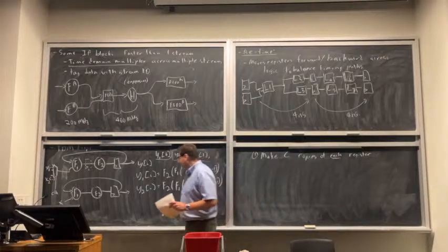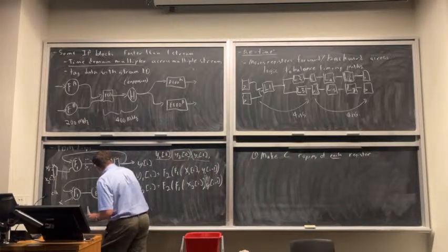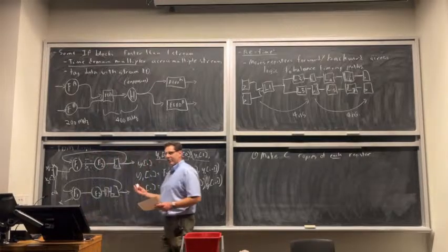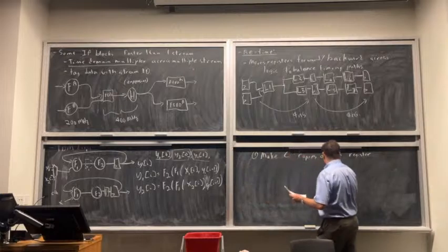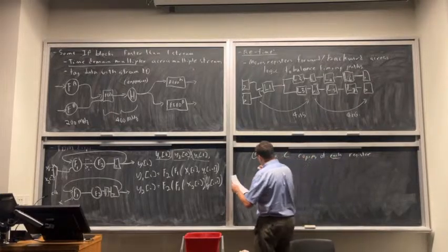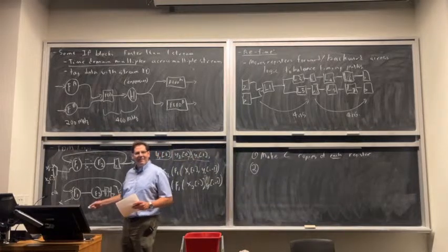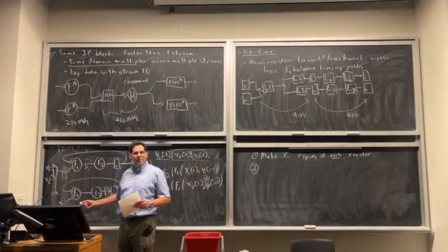Yeah, so series is what makes sense. So I take this register and I basically make 2 copies of it. Okay, so now there's 2 registers. So that's my first step. If I stop here, I broke the circuit, okay, because I can't do that. I can't just change the pipelining of this.